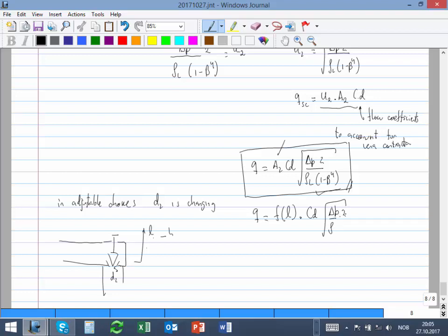Like you see the equation, where it came from, what is the shape that I have. So this long message is just to tell you, if delta P is fixed, and this is L, the travel, we call it the travel of the stem of the valve, and this is Q. If L is 0, it's completely closed, so I have no flow. And if L is 1, or L the total traveling distance of the valve, then this is open.